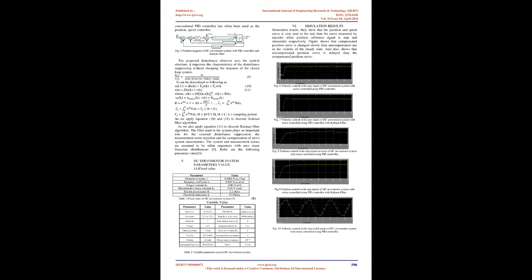The servomotor has two main components. The first is the electrical component, which consists of resistance, R, and inductance, L. The second component of the servomotor is the mechanical part, from which we get the useful mechanical rotational movement at the shaft. The mechanical parts are the motor's shaft, KT, inertia of the motor and load inertia, J, and damping, B. Theta refers to the angular position of the output shaft, which can be used later to find the angular speed of the shaft, W.